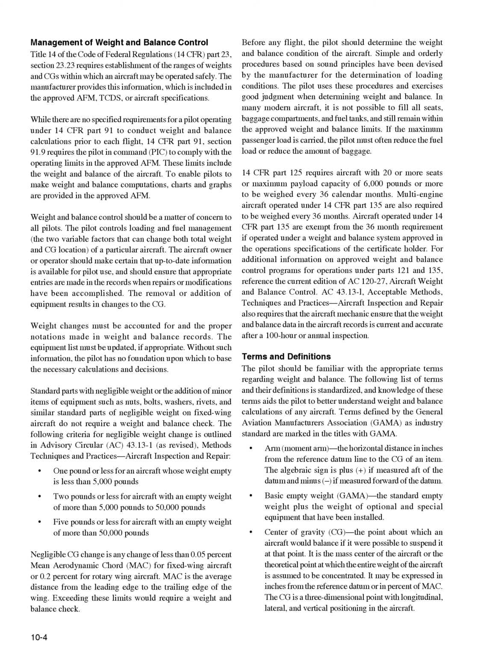In many modern aircraft, it is not possible to fill all seats, baggage compartments, and fuel tanks, and still remain within the approved weight and balance limits. If the maximum passenger load is carried, the pilot must often reduce the fuel load or reduce the amount of baggage. 14 CFR Part 125 requires aircraft with 20 or more seats or maximum payload capacity of 6,000 pounds or more to be weighed every 36 calendar months.